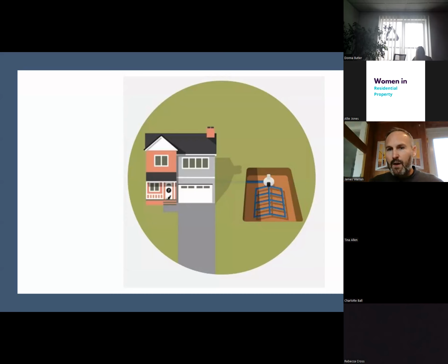What we're looking at now is an illustration from 2015 onwards in England. If a septic tank has been installed, it has to look like this. So if we look at the white onion, we're saying that's the septic tank. They come in all shapes and sizes, but this is just for this illustration. The white asset is the septic tank. The little black asset in front of that is called a distribution chamber, which must be there. The regulations state they must have a distribution chamber.